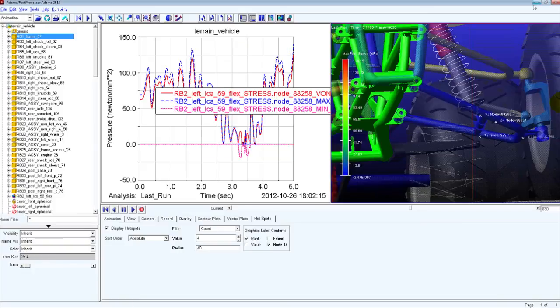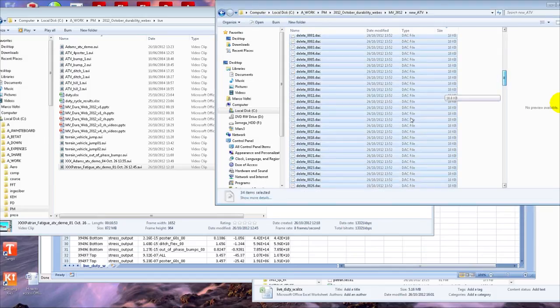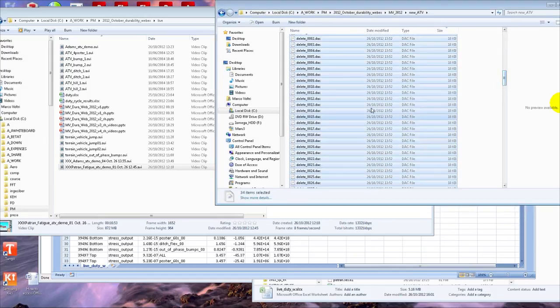What happens is that as soon as we export the modal participation function, we had a total of 34 modes, so we expect a total of 34 modal participation functions, and all these are going to be used to load our components in Fatigue. Okay, so let me just briefly go back to the PowerPoint to introduce what is coming next.